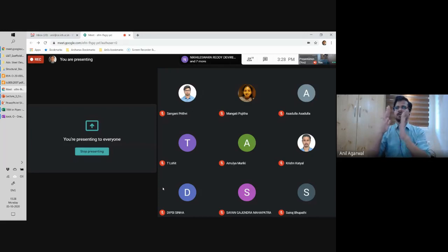Now, let's say I have an I section, and this is the web of the I section. You can see my hand. This is the web. You have one flange here, one flange here. It is much easier for me to provide a rigid frame in this plane. But providing a rigid frame in this plane basically requires me to connect this member to the web of the column. And that connection is not easy, because if I just connect to the web, it will not really be rigid. The web will be undergoing a lot of deformations. So then I have to make a very complicated connection here to make it behave like a rigid connection.